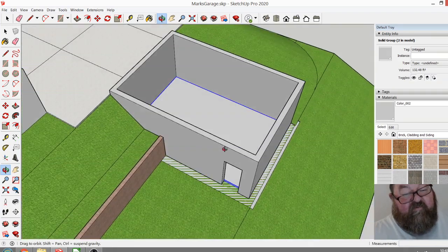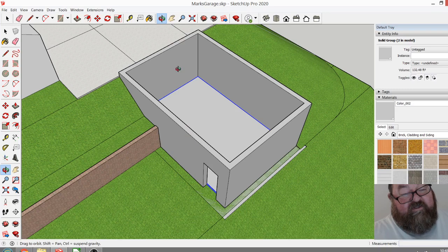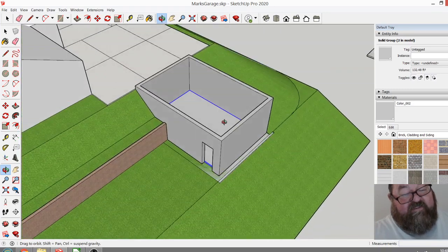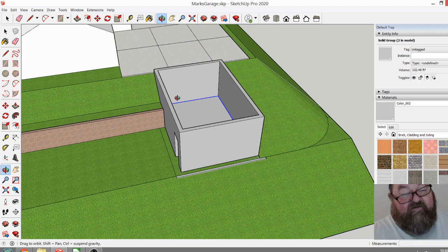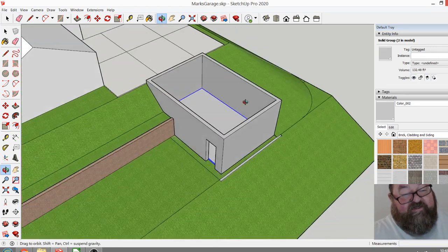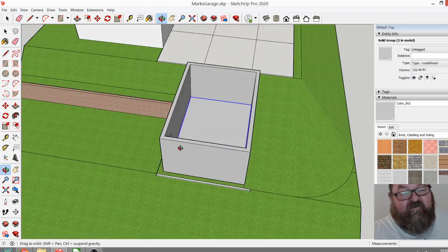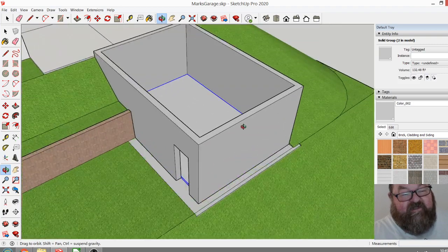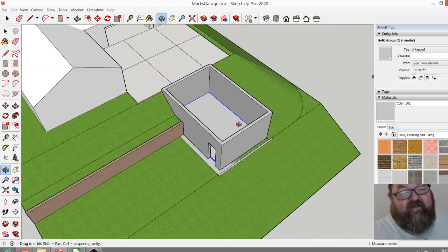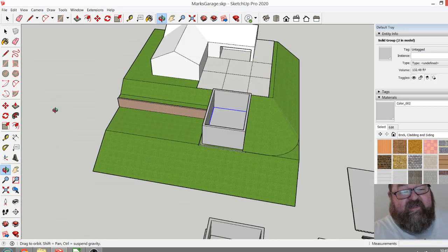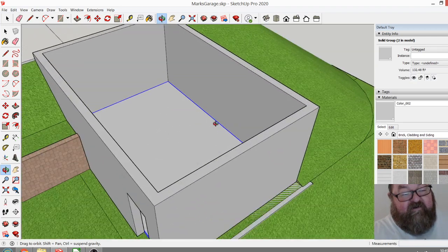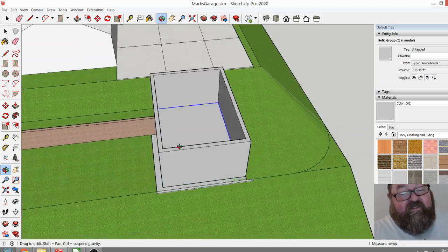And right now, this is what I'm proposing: if you're going to go through all this trouble, sometimes this is kind of a one-shot deal, right? You need to make this garage as big as you can make it. Instead of making it 18 by 24, make it 20 by 26 or 20 by 28 if you can, because it's not going to cost that much money. What costs you money is all the staging it's going to take to get big equipment down this tiny driveway. Okay? And this is really me talking to the owner now. You want to really think about this.